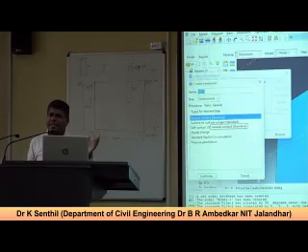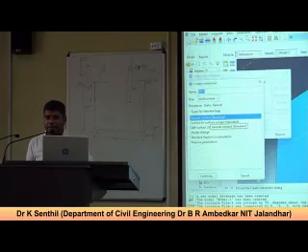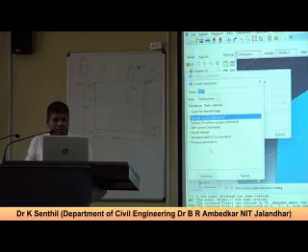But you can go for explicit analysis. Sometimes some of the models may not support explicit analysis. Suppose you are going for a concrete pile, then you better take it as rigid and don't define the steel reinforcement and other things in the concrete, because the static general may not support the Johnson Cook model. So like that, some constraints are always there, so you have to look into it.